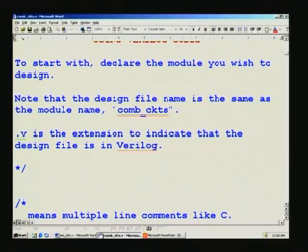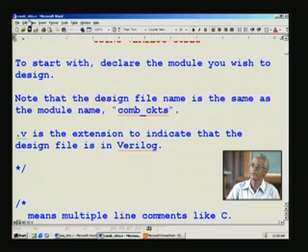So, make it a habit to use the very same notation even for saving it as a file. For example, the file, I wonder whether you can read it here. I will just read it for you. It simply means com_circuits.v. So, do not forget the extension .v to indicate that it is a Verilog and not VHDL. In VHDL you say VHD as such. So, .v is the extension that you have to give for any meaningful name that you have here.